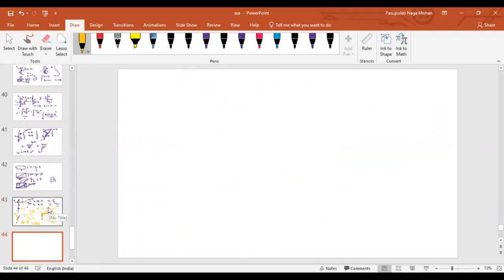Did you understand the logic? If the member does not have any moment, the deflected shape of the member will be linear. That means the slope of the member will be constant everywhere.